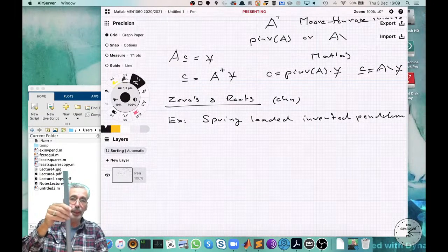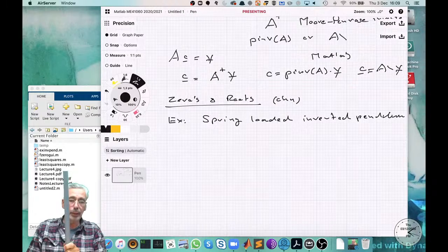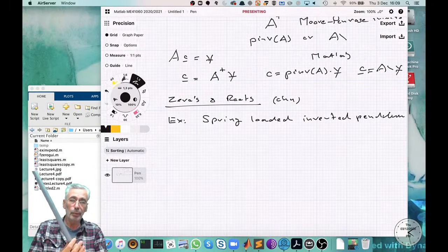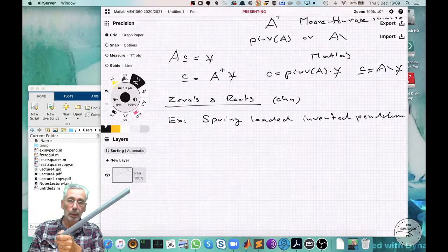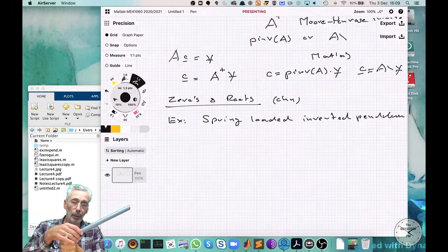But what you could do as balancing, you could add a controller here, and the controller is my hand. Well, what does my hand do? It has a certain stiffness. So the moment the thing starts to move in this direction, my hand supplies a torque. Or if it moves in this direction, my hand supplies a torque. So gravity is pulling on the one hand side, but my hand is giving this restoring force. So that is spring-loaded, and by this spring-loading I can keep it in this position. If the spring is very weak, it will find another equilibrium position, right? It's a very weak spring.